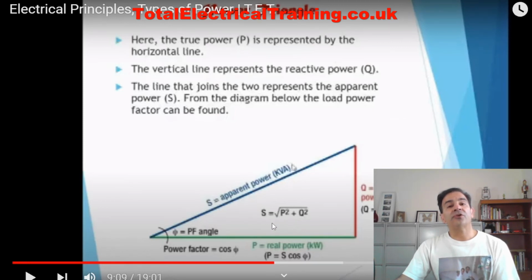So you need to correct the way your meter shows by bringing the kilovolt reactive, this red line, down to almost zero. Now, bringing it down to zero exactly is almost impossible in practice. To tell you why, it takes a big lesson, and you need to have the electrical background.